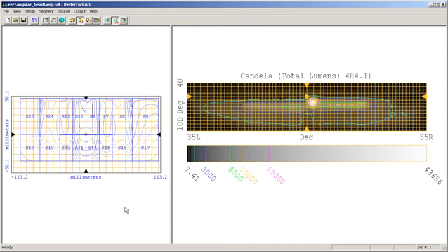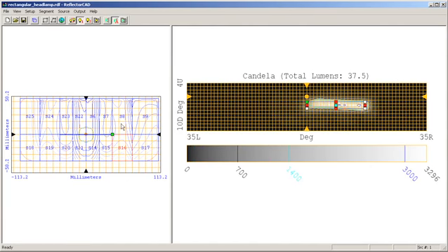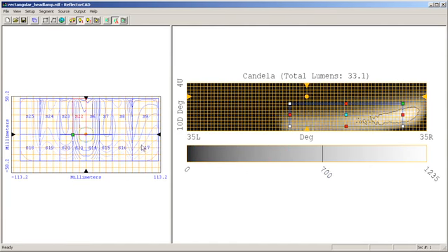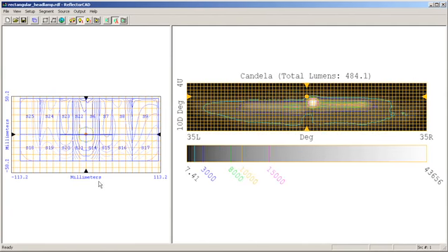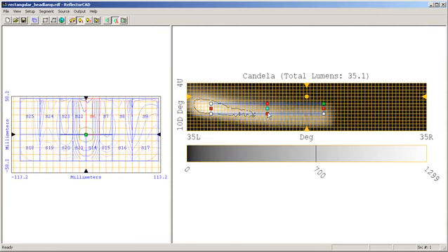ReflectorCAD allows you to graphically lay out the reflector segments, to compute very quickly the approximate intensity from individual segments or all of the segments in a source, and most importantly, to graphically adjust the radiometric output from each individual segment. ReflectorCAD then automatically will adjust and create that segment corresponding to that particular radiometric output.